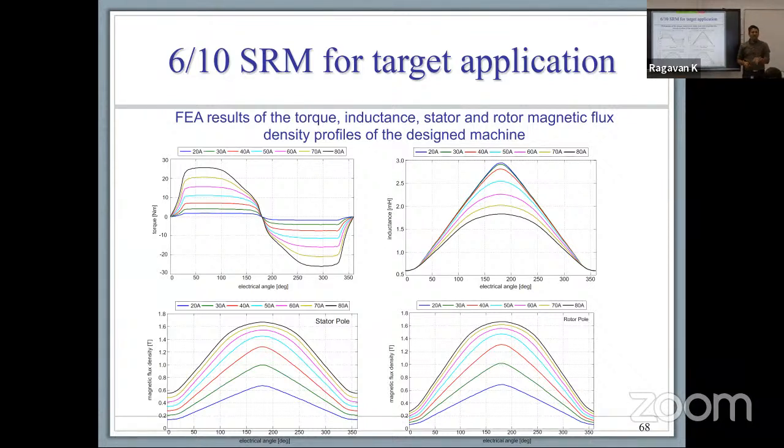Now, it's a little more complicated than that. It's not quite as simplistic, but effectively that's what you're doing. You get torque from one rotor, you put the next one, create enough of an overlap so when they start to drop, one's dropping, the other one's picking up, the sum still stays where your tangential force, it adds, right? Normal forces don't add, but the tangential forces do add. So the ability to add the tangential forces means as long as you have a good amount of overlap, you can get a very good performance.